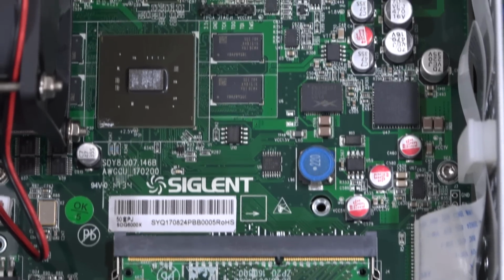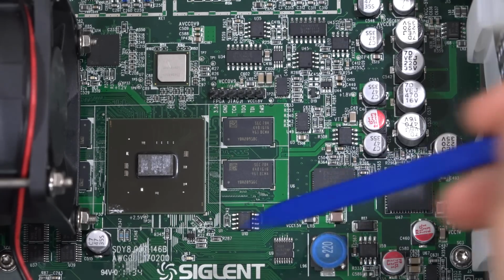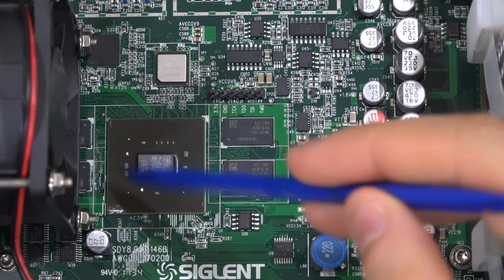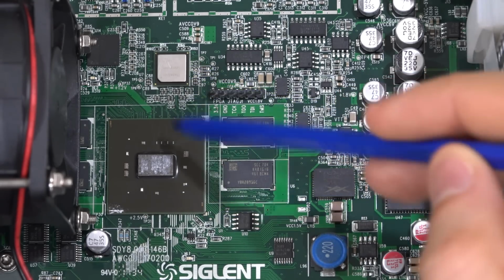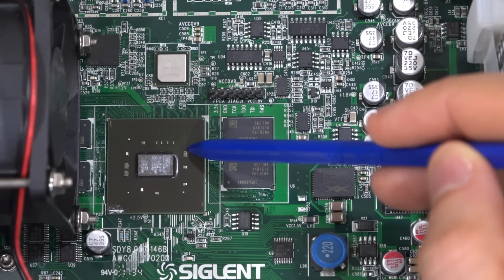So let's go ahead and look a little bit higher up here, so we can see some of the more interesting circuitry. So putting aside the interface to download data onto the FPGA, really the FPGA's job is to communicate with the DAC, and the DAC is right over here. The FPGA is going to require external memory because the circuitry inside the FPGA itself is not designed to hold so much data.